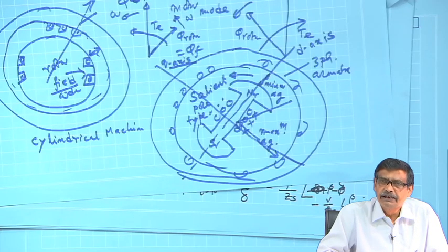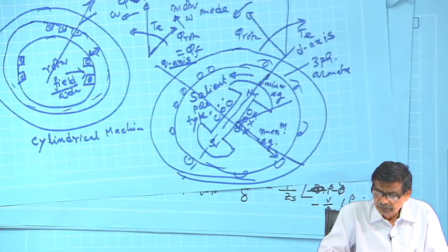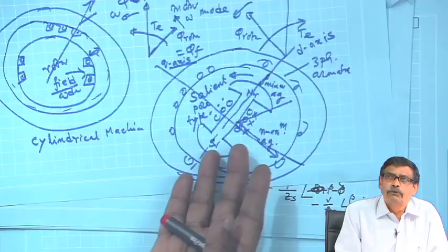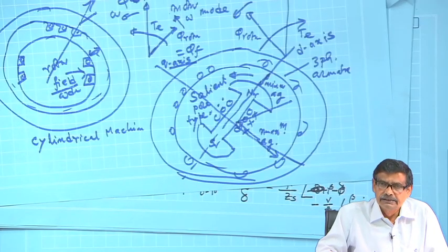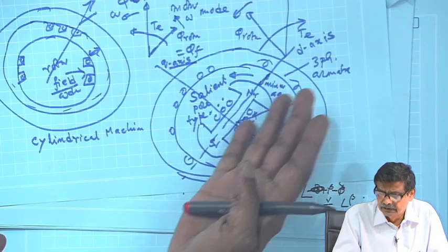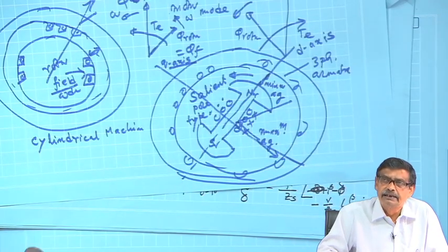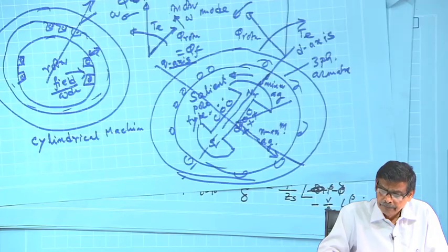Therefore, to calculate the flux for different positions, you have to divide this MMF by reluctance, which is position dependent. Therefore, it is very difficult to model. Is it then that wherever it is, I calculate precisely the reluctance, divide by it, and get the armature flux? It is not really like that.